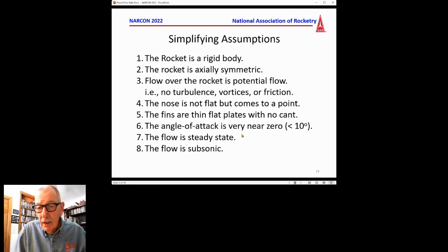If they're analyzing it as a subsonic rocket and it goes supersonic, or at least close to the speed of sound, the center of pressure is going to change, and there again it moves forward. So the distance gets smaller, and therefore you should have more static margin. So those were the assumptions.